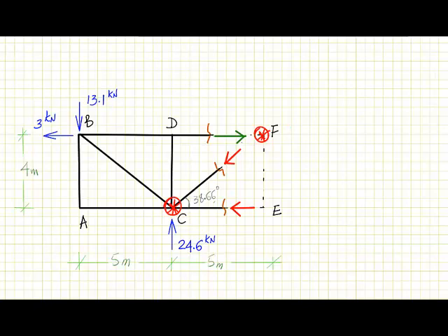So we can start by taking the sum of all moments about point F. The sum of all moments about point F is equal to 0. This is the equilibrium equation that we'll be following. Before we do the sum of moments about a certain point, we need to define the rotation direction for each force. We are taking moments about this point, so these two unknowns will be cancelled. We don't need to bother about these two for now.